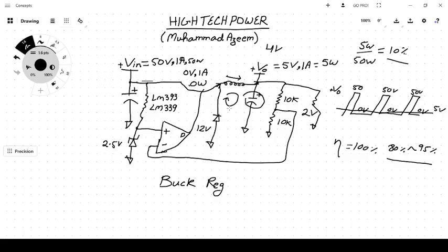And the other type of power supplies are where we insert a transformer instead of an inductor in between, so that the input ground is not connected to the output ground and is isolated. That is used where the input voltage is at a much higher level, just like a household voltage, and we don't want to create hazardous situations, so we isolate the output voltage from the input voltage.